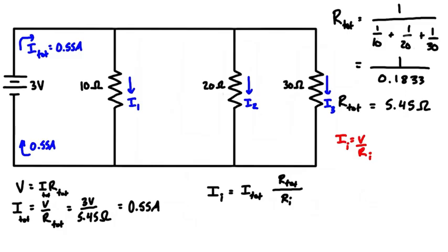So we can update that. We have the individual current through one resistor is equal to V, which is I tot times R tot, over Ri. But you can see that we can pretty much just have I tot times R tot over Ri, which is what we have here. Sometimes this is the more common way that you see the current division formula. So anyways, let's erase this rough work, but it's there in case you needed to see how we get this.